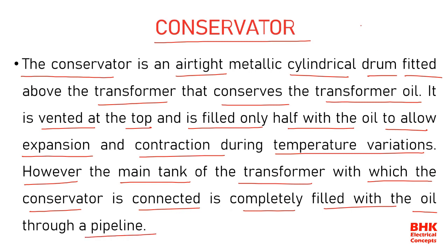Okay, it means what? For example, this is the conservator. Initially, we are filling only 50%, because whenever the oil expands inside the transformer, the quantity of this particular oil increases. So due to that, we can observe that something is happening in the transformer. So with the help of this conservator, we can easily analyze the running condition of a transformer.